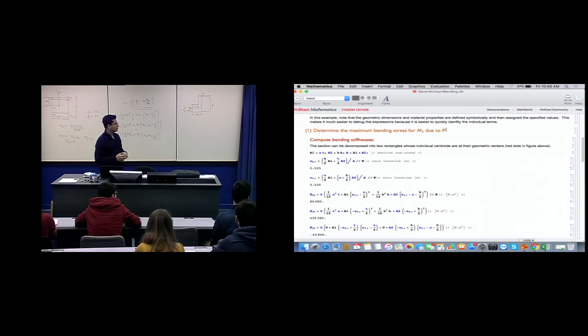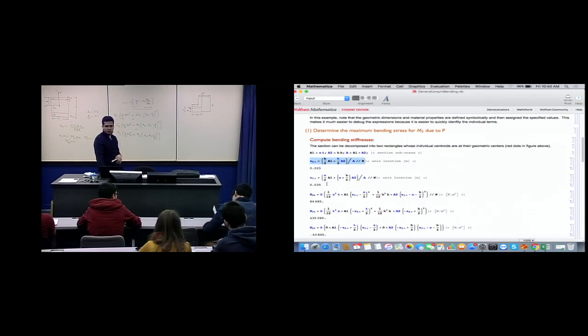So we have to identify this expression, which is now not going to have just H33, it will have a component of H23 as well. So we have to identify that and then solve the problem. So the steps remain the same. First we evaluate the centroid, which is being done here. And as we know that there is no plane of symmetry, so we have to evaluate both x2 and x3. Right? We cannot make any judgment on where x3 should be. So here we evaluate x2 and x3.